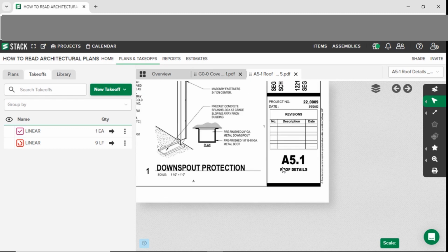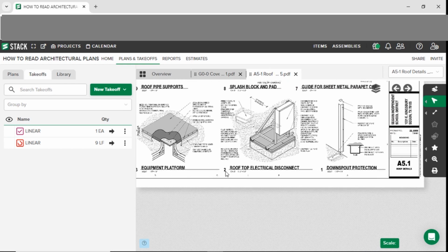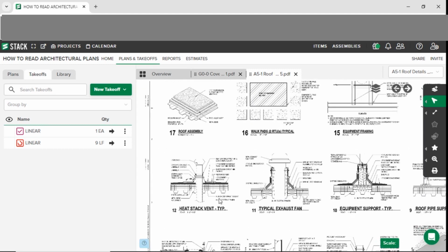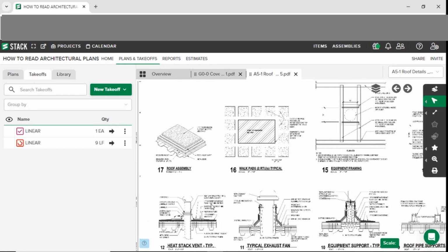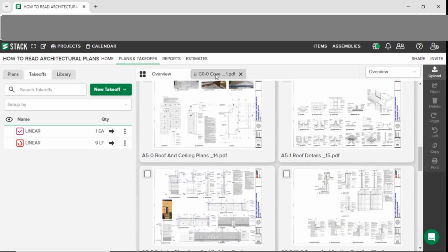You'll eventually go to the sheet number. It won't say reference, but it'll show you the way it showed you that elevation. It'll say, like right here, A5.1, which is a sheet, drawing number 1, drawing number 2, drawing number 3. If that's the drawing that you need, that is directing you to obtain that information, that's how they'll be labeled, not just for an elevation, for any type of detail.